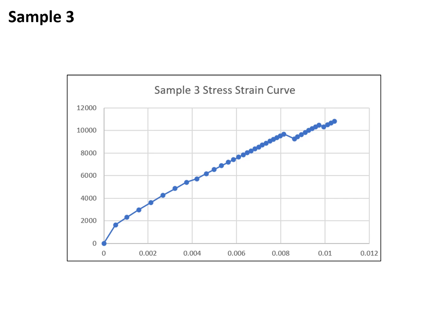From the previous two samples, we saw the stress-strain curve to have a linear portion first, then a negative quadratic curve. This curve is simply just linear, and even the data on this curve is not reliable, as I discussed earlier. Therefore, this wood sample is undeterminable. If I were to redo the sample, I would have to make sure the sample stays in the grip to